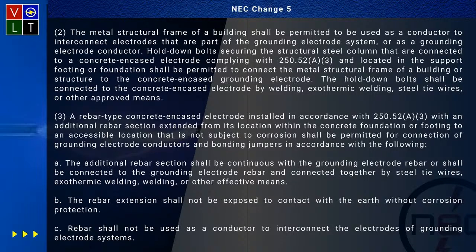And if you go look at 250.52A3, it says if I take and I run a conductor in there and I put 20 foot in there, what size does that need to be? Number 4. Number 4, yeah. Right. And then if I go look at 250.66B, I'm leaving there. What size does it need to be? Because you're connecting to that number 4. Number 4, isn't it? Yeah.